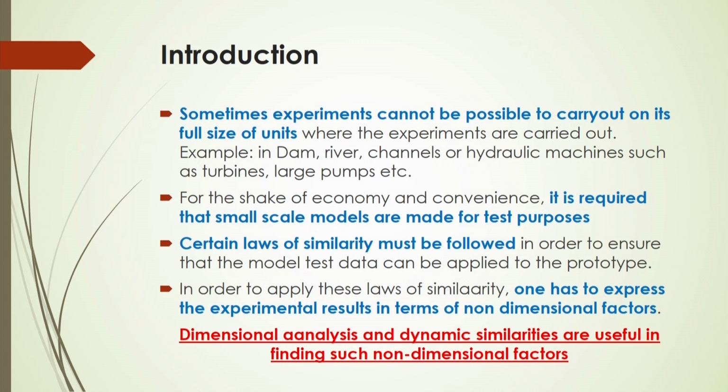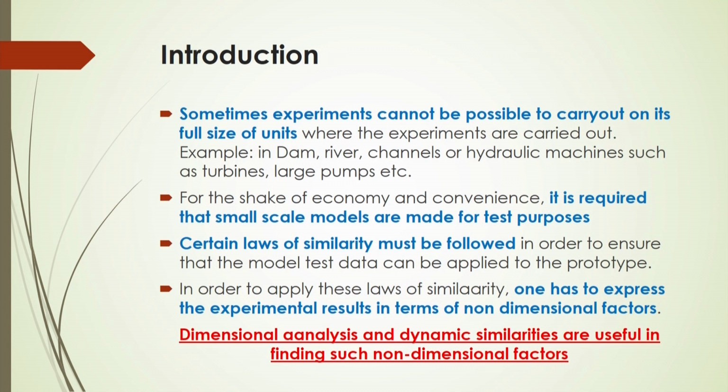If you consider a dam, river, channels or hydraulic machines such as turbines, or sometimes large pumps, it is very difficult to do the experiments. So, to know the phenomena of that dam, river, channel or hydraulic machine, you have to do some experiments on those flow phenomena on a small scale in the laboratory. Based on that laboratory scale physical phenomena and interpretation, you can scale up those data to design or analyze the system which is a large unit like a dam, river, channel and other hydraulic units.